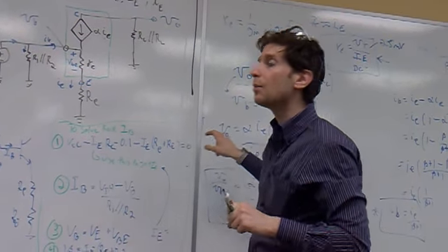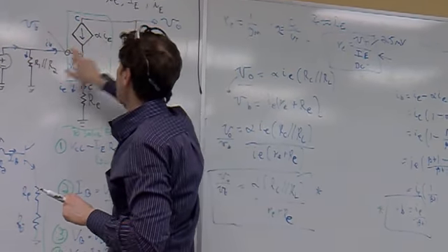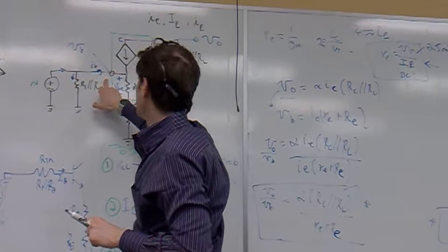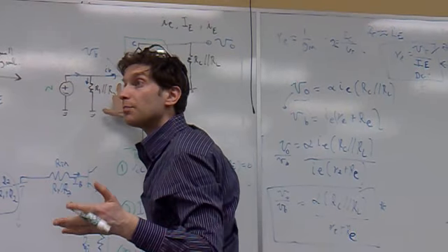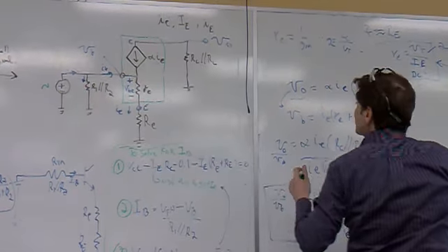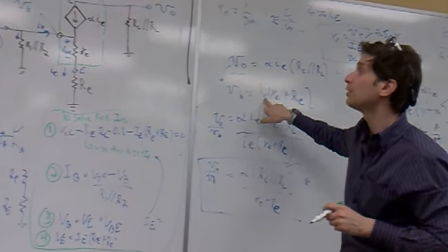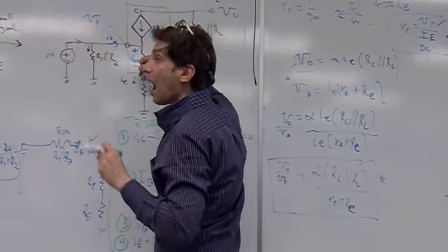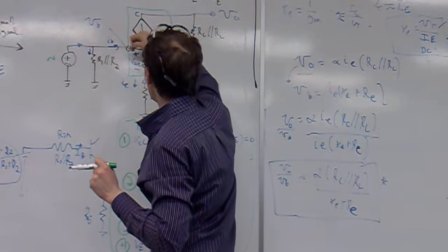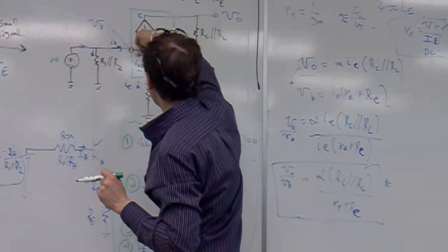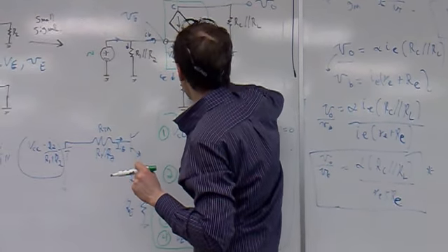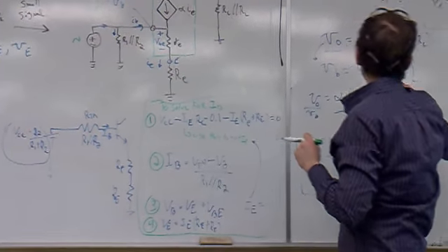What about the gain? How do we define gain? It's this divided by this. The output divided by the input. V out by V in, which in this case happens to be VB. What's VB? It's equal to i little e that goes through here, which goes through little re, which goes through capital RE. So we have this.